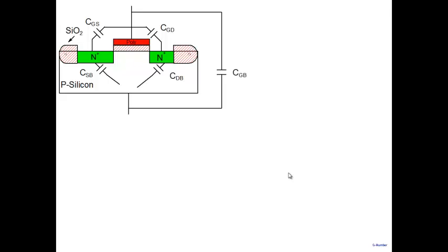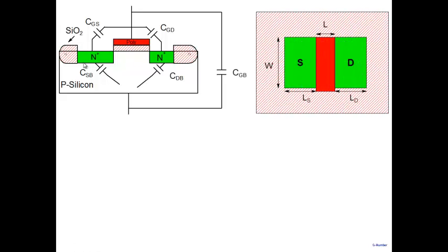So coming back, if we go back here and focus on this PN junction capacitance, there is a capacitance that will come about because of the area of this junction. There is another capacitance that will come about because of the perimeter. There's a perimeter here, a perimeter part here, and a perimeter part here. So there are going to be field lines here all along this edge.